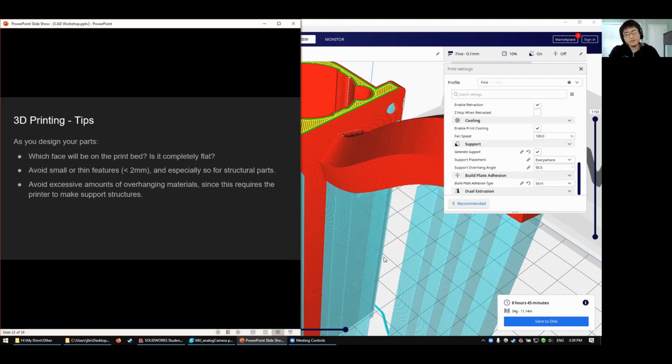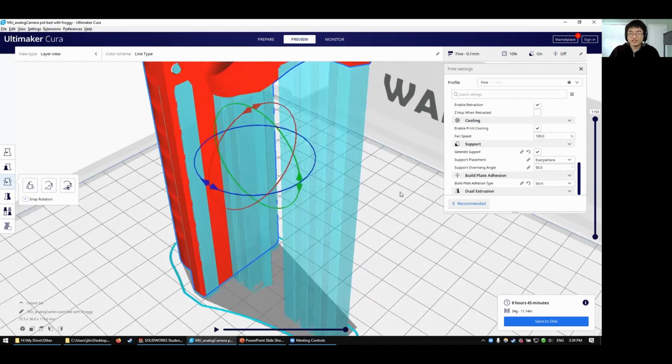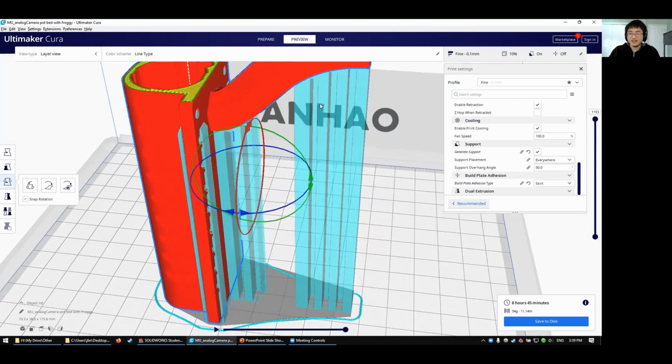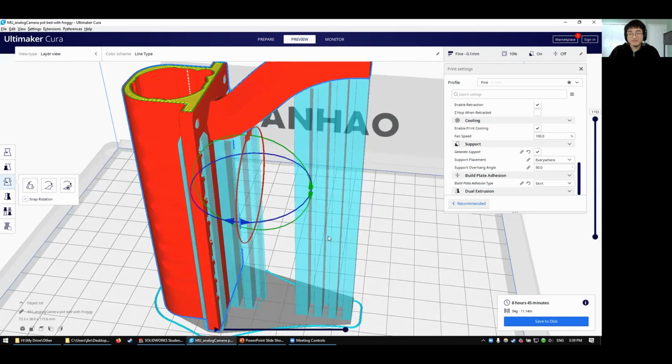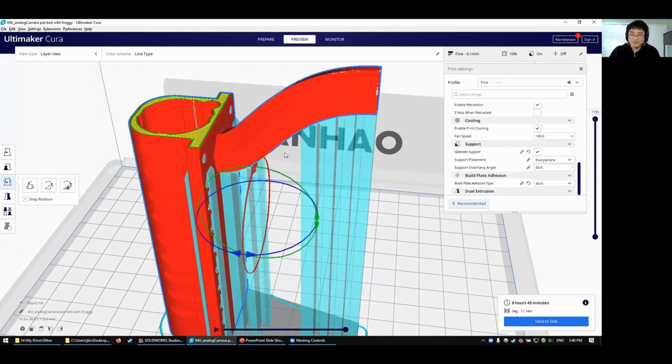Usually if you're designing a 3D printed part, you want it to extrude in one direction for the most part, have some details maybe, but not too much overhanging in midair. Otherwise, you will have this guy right here with a humongous amount of skyscraper level support needed. So try to avoid this. It takes a lot more plastic, I suppose, but also a higher chance of failure. Maybe if the plastic gets too heavy or something, or maybe it doesn't adhere right over here, then it could fall off. And then your 8.5 hour print has gone down the drain, unfortunately. So try to avoid a lot of big supports needed.